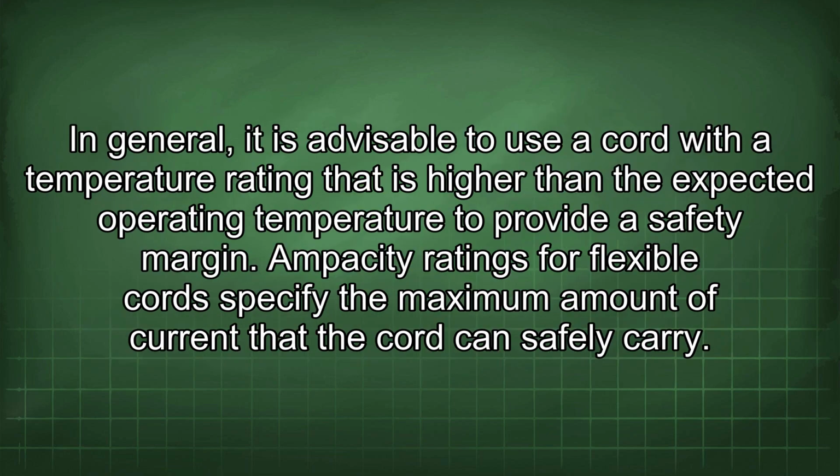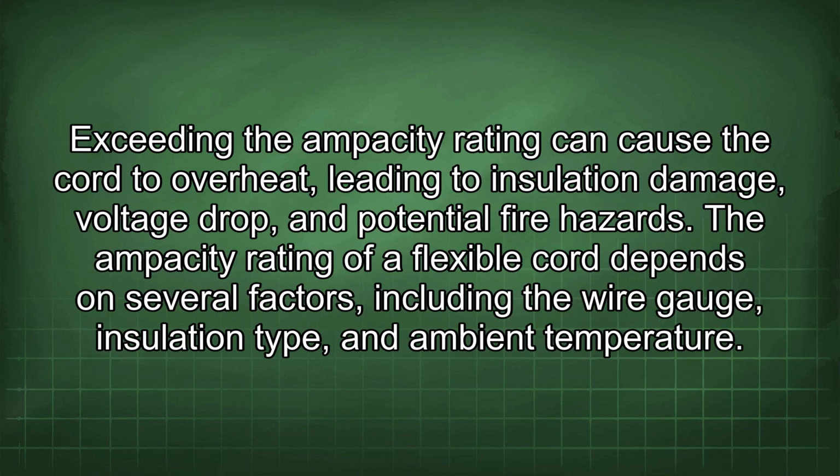In general, it is advisable to use a cord with a temperature rating that is higher than the expected operating temperature to provide a safety margin. Ampacity ratings for flexible cords specify the maximum amount of current that the cord can safely carry. Exceeding the ampacity rating can cause the cord to overheat, leading to insulation damage, voltage drop, and potential fire hazards.